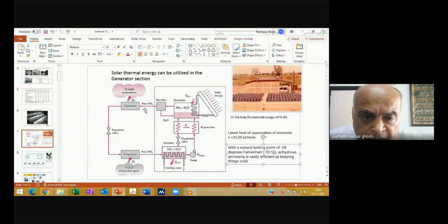the heat, because it's all hot, is getting radiated to the environment from here. So this is another place where heat is going out of the system. Make a note of where heat is going into the system and where heat is coming out of the system. Here heat went out, here heat went in, here heat went in, here heat went out. So as this thing is getting cooler and the pressure of ammonia is high, it will start liquefying. It condenses into a liquid.